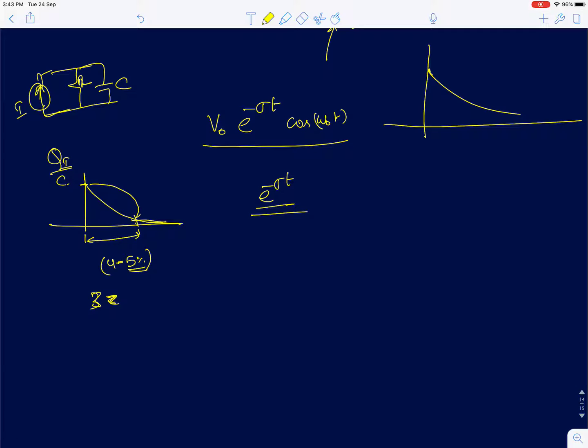If you watch one of the previous lectures where we discussed first order RC circuits, you can see that after 3 time constants, the exponential decay is very fast, so it's going to decay down to just 4 to 5% of its initial value, or even lower. So from that, I'll compute the value of 3 time constants by just looking at the time for which the value becomes 4 to 5% of its initial value, and from that I can calculate the time constant of this RC circuit.